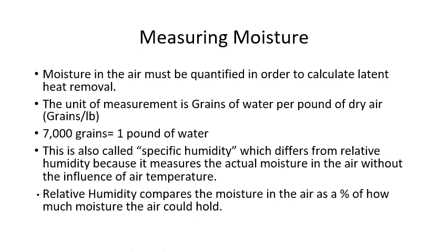Think of it like a sponge. If you have a dry sponge and you pour some water on it, let's say you pour a cup of water on a very large sponge. The cup of water is your specific humidity. When you pour that into the sponge, that sponge is either 10%, 50%, or 100% filled with water. That's your relative humidity, how much water that sponge can hold compared to how much water is actually inside of it. So it's a percentage.